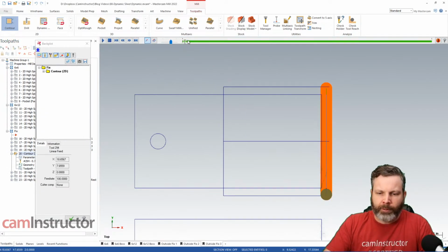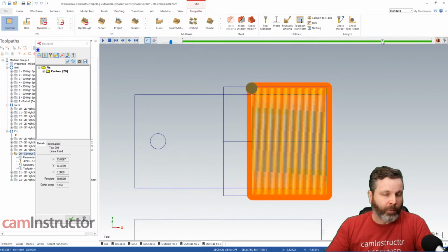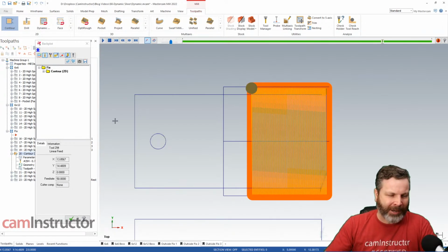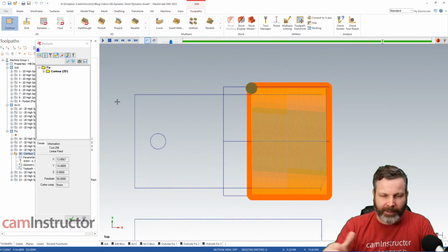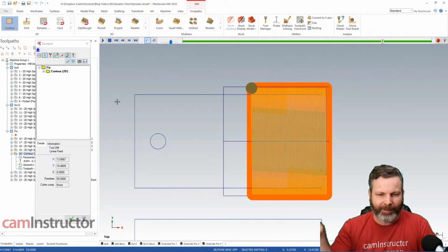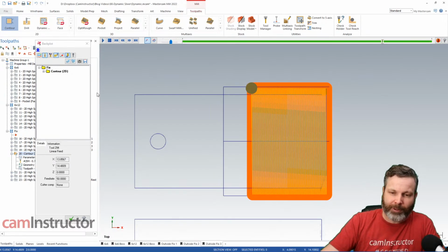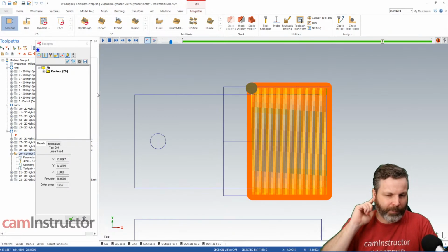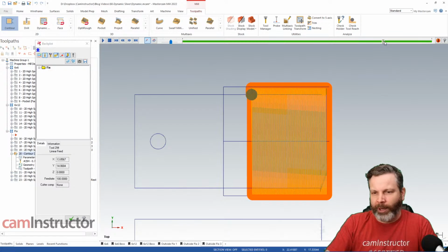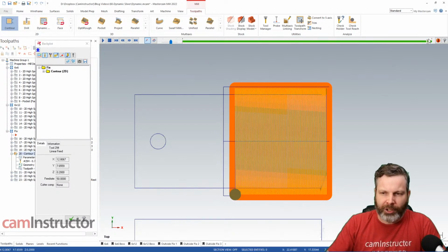So with contour, it's doing just straight zips across, retract, reposition. So lots of retracts. There's no way around that. Okay, I'm saying that wrong. There is a way we can get around not retracting, and that would be by doing a zigzag cut. But my argument would be, again, if you're in a climb mill scenario and you've got this cutter right on the brink of breaking as is, you're not going to want to conventional cut that cutter at those same values. So bad things will happen there. Cutting forces in climb milling versus cutting forces in conventional are much different on the cutter, and conventional probably won't go so well either. But then again, that's just a way to attack that material to get it back to a more square-ish size so that the dynamic then works the way we like it to work.